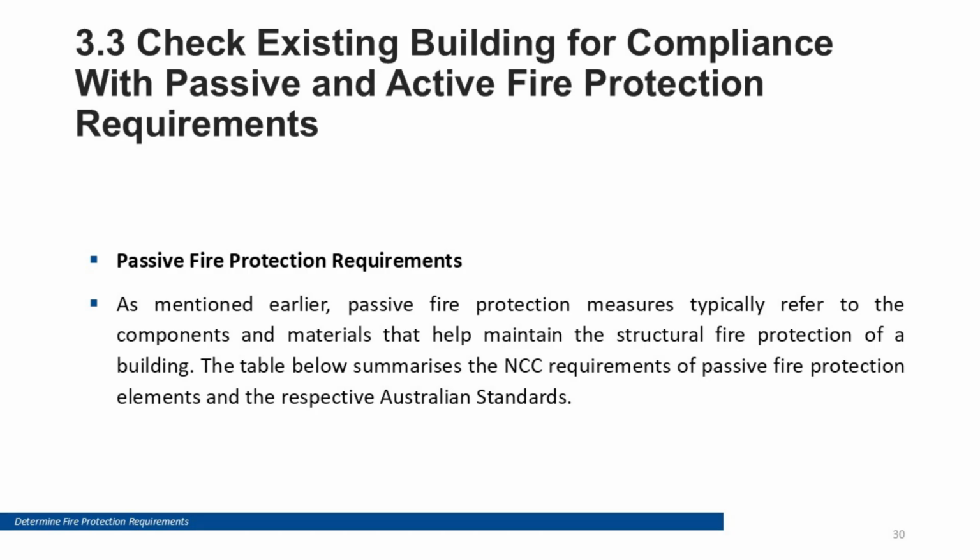Check existing building for compliance. Checking compliance means confirming both passive and active fire measures meet NCC and relevant Australian standards. The practical approach is identify what systems are required, confirm what is installed, and document gaps for rectification, so compliance can be demonstrated.